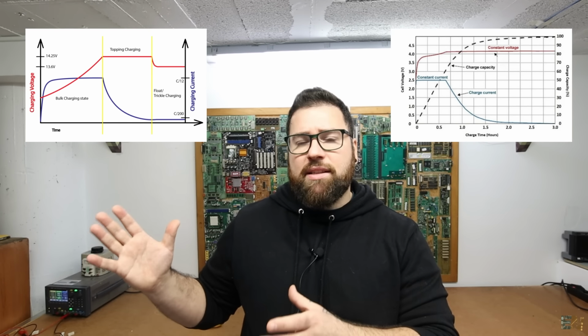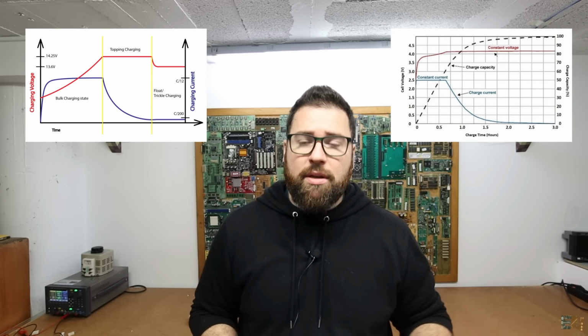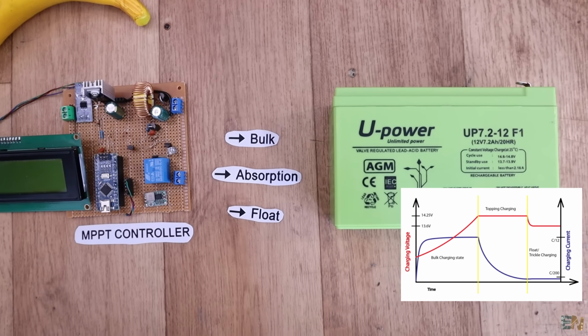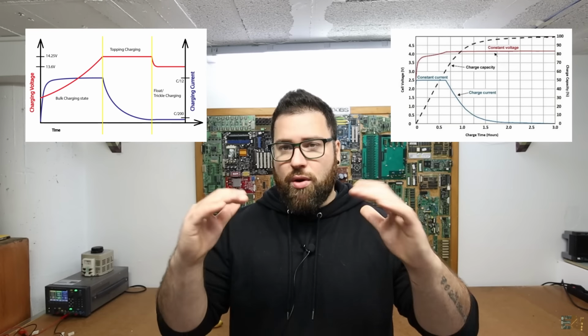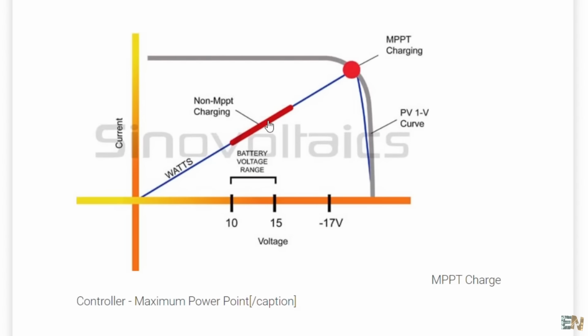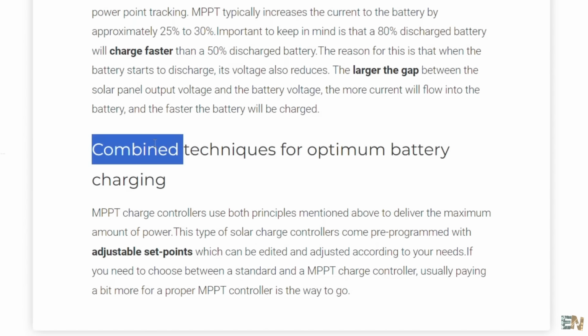And some of these lead-acid batteries will require a bulk time, absorption, and then a float time, so you have to make a ramp, which is not MPPT. Once you have the ramp, you can float it or maybe make the absorption time, which could be MPPT, and then you just maintain that voltage using MPPT or any other controller. So usually these drivers will choose which kind of controller they will use each time. So it's better to have an MPPT, but it's a lot better to have a mix of those two.